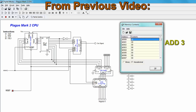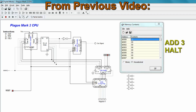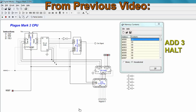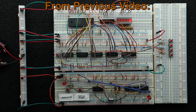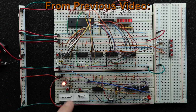Then I removed the no-op instruction, which then made add 3 the first instruction in memory. This should not have changed the result of the program execution, since a no-op doesn't do anything other than to waste a clock cycle. But, as we saw, the program no longer gave us 2 plus 3 as a result. The simulator gave us a result of 0. Then I tried it on the actual hardware, and after a reset, register A held the value of 3 instead of 0. Other than that, it executed the same as in the simulation. Register A did not change after the add instruction was executed.